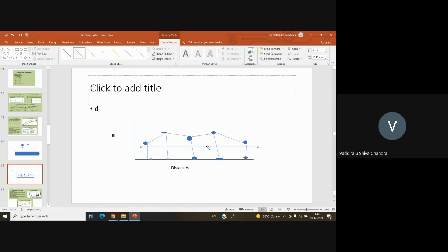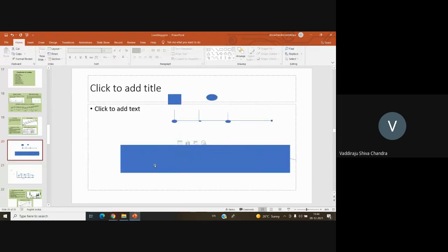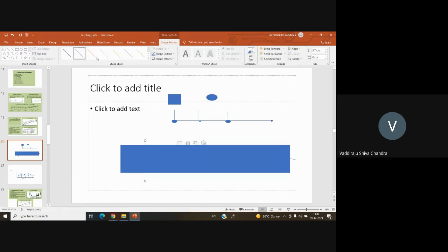Along with the longitudinal leveling, we'll also be doing the cross-sectional leveling, because in this figure, this is the stretch I'm taking. I'm taking the readings along the center line. But in order to calculate the volume, you also need this portion, right? So for that, at the same 5-meter or 10-meter interval, whatever interval you want, we'll be taking the staff readings perpendicularly also.